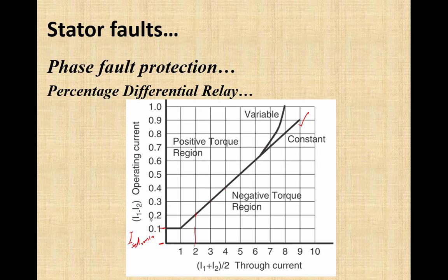In case of a simple overcurrent relay, we only have this I set minimum current, the only setting. So it means the overcurrent differential has a characteristic like this horizontal line. As soon as the difference current becomes greater than this level, the relay is going to operate. Now if I show you the difference current for different values of retaining coil current in a practical CT, that trend